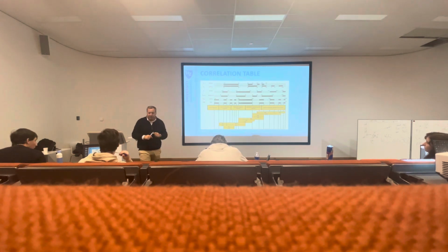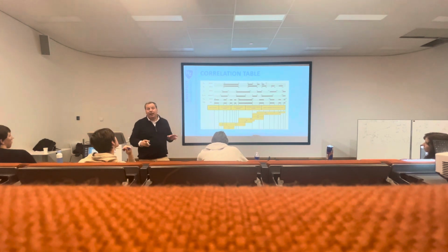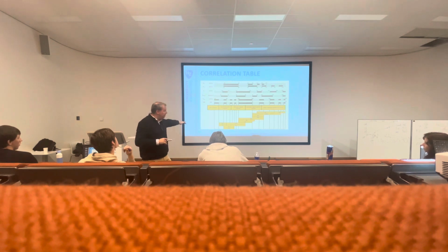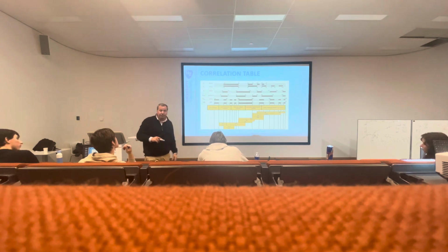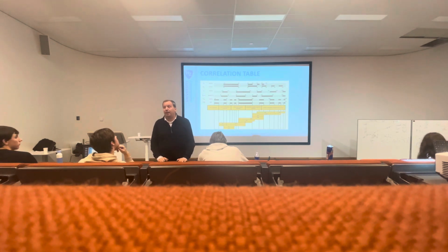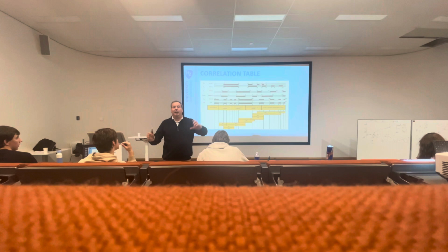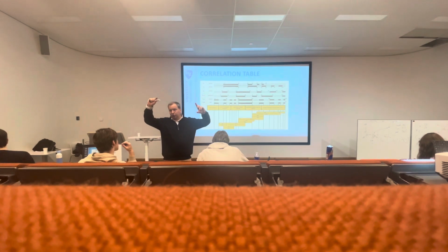So these values are telling us something about the elastic modulus or the bearing capacity. All this data that you see, except for the soil type, are factors that are used only to say something about the bearing capacity. So, in other words, the CBR value, California Bearing Ratio: in the 1930s in California they did a test with rocks, and they looked at how much the soil sinks when you put a load on it.